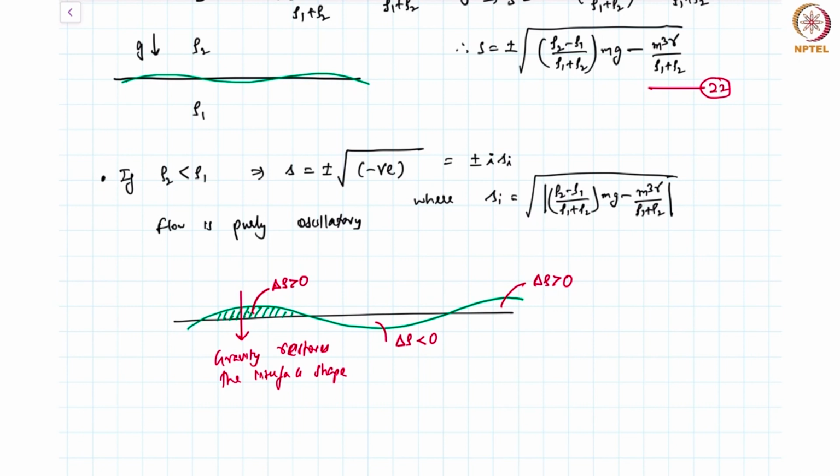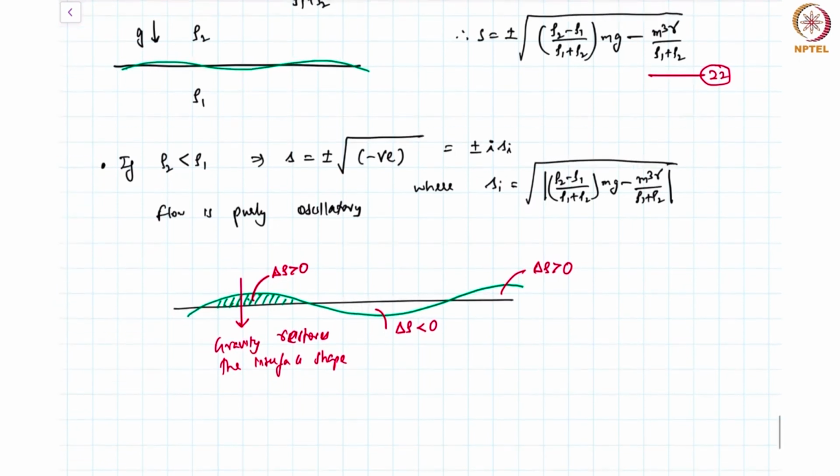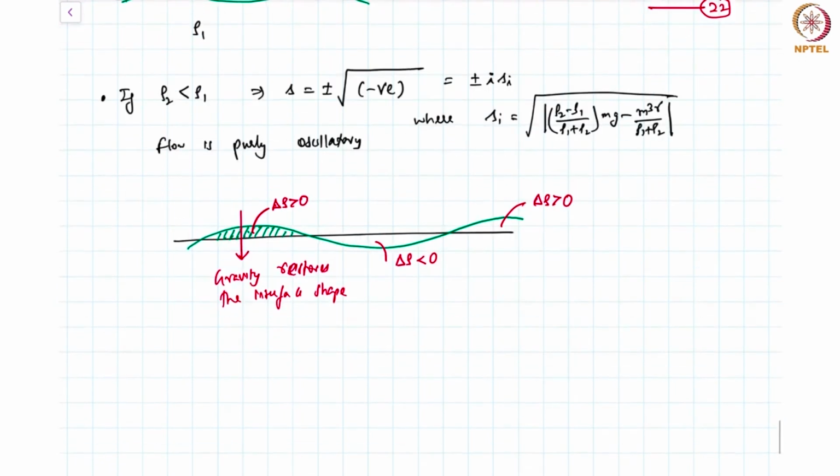So essentially the moment you perturb the surface, you are paying a penalty as far as surface energy is concerned, and therefore surface tension will try to kill the interface perturbations. It will try to bring it back to its original horizontal state. That's what surface tension will try to do. In this case, gravity is assisting it, when the fluid above is lighter than the fluid below, right?